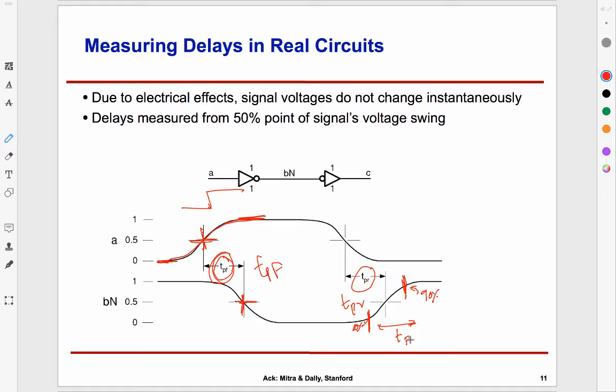That's not good. The second reason, which I alluded to earlier: if my voltage is rising very rapidly, that is saying something about the current movement. So instantaneously, I'm going to see a big current spike. And the third reason, which relates back to the second, is that if I have a sudden rush of current draw from the power supply, then it has many bad effects.